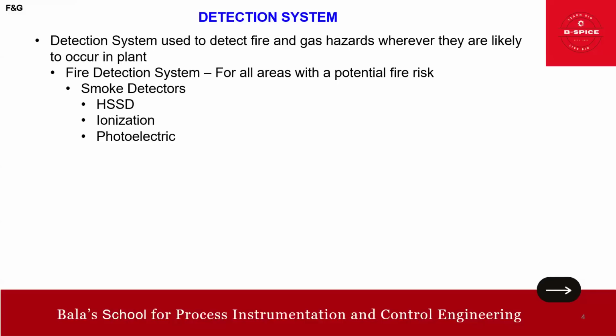As we all know, a photoelectric detector is a device that uses light to detect the presence, absence, or distance of an object. It typically consists of a light transmitter, probably infrared, and a photoelectric receiver. When an object interrupts or reflects the light beam, the detector senses this change and triggers an action, such as sounding an alarm or stopping a machine.